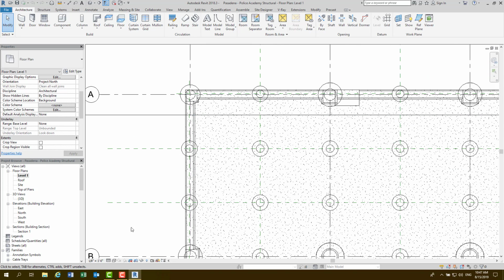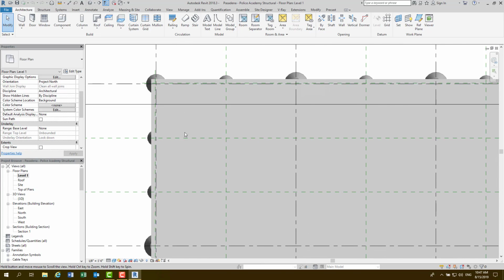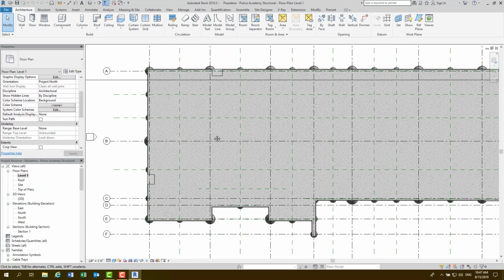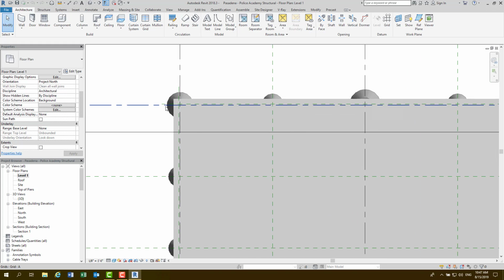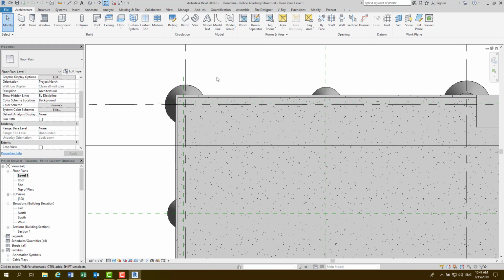So I'm looking through a wireframe view at the bottom. If I want to change this back to a shaded view, that way I don't see through everything. You can kind of see top down what I'm looking at. So I need to put some hollow steel columns around the outside, so I got to look at my drawings to see which ones I need to pull in. It looks like, according to the drawings here, that I need some 6 by 6 by 3/8, some 5/16.